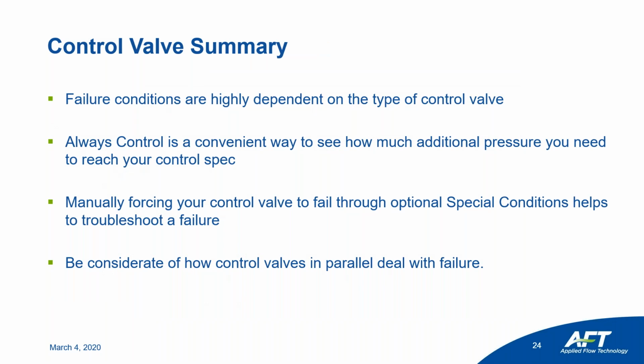So failure conditions, highly dependent on type of control valve, especially when you're looking at excessive downstream pressure or insufficient upstream pressure. Whether it opens or closes depends on the valve, or if it closes at all in the case of a constant pressure drop. Always control is helpful, especially if you're doing valve sizing and you need to figure out how much pressure you would need, but it can also be a pain, causing valves that wouldn't fail otherwise to fail.